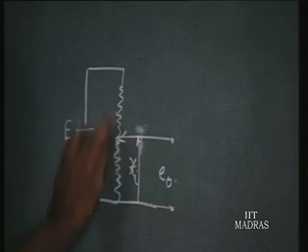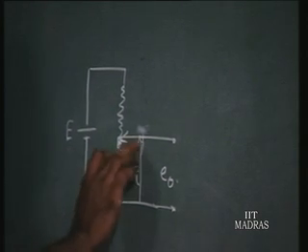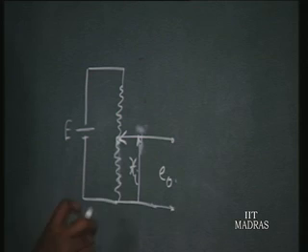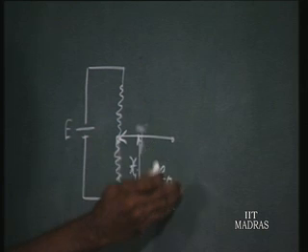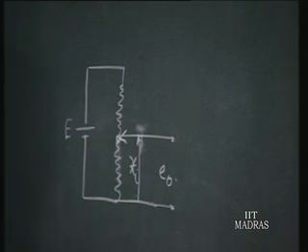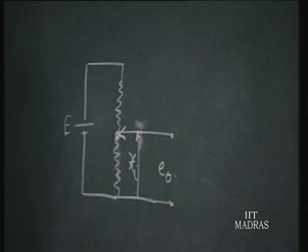This whole voltage is proportionately distributed along the resistance, and when we move this contact up and down, proportionately we have got a voltage output. So if so many millimeters of motion is equal to so many volts, we get it here. That is how we transduce a displacement into a corresponding voltage.